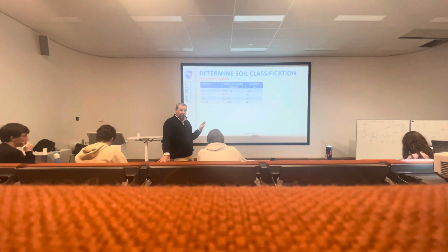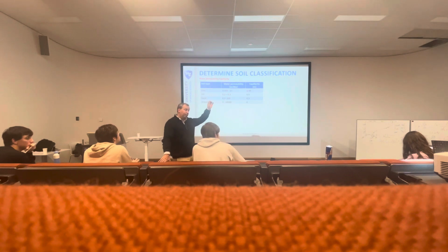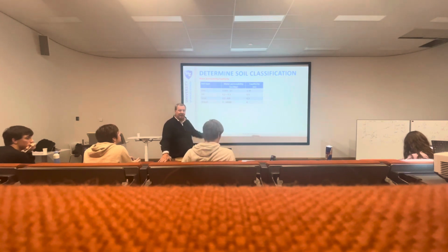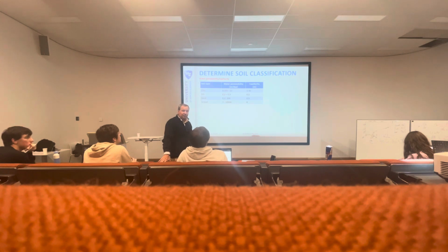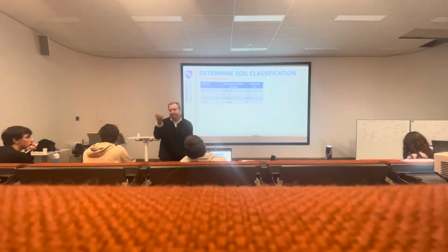There are some laws which say you cannot percolate rainwater to the subsoil, even though you could make some holes in the soil to get it to the sand layer beneath. But the problem is that rainwater can be contaminated, and then by law it's not allowed to induce rainwater into the groundwater, because groundwater we use to drink, and with rainwater we're not sure about the quality sometimes. That's why we cannot put it in. But for many people it's strange when they say the groundwater level is actually still not good enough, because of the clay layers.